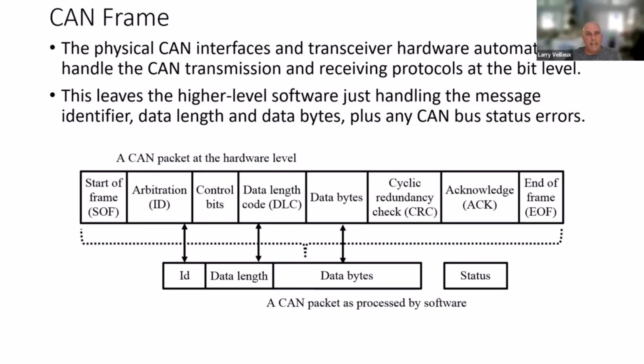All right, well, let's look at a CAN frame. Okay, so now we're up at the data link layer level, right? And so that's where we actually frame the bit into fields. If you've studied protocols and stuff like that, this is something that's familiar with you. The fields are generally broken up. Some of the fields are used by the physical layer, for instance, such as the start of frame field, and even the arbitration ID to a certain extent, although that's shared somewhat with the data link layer as well.